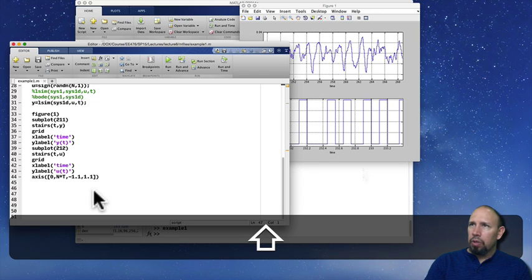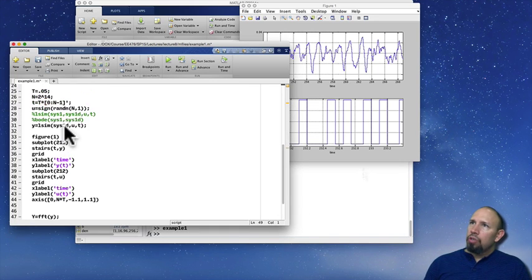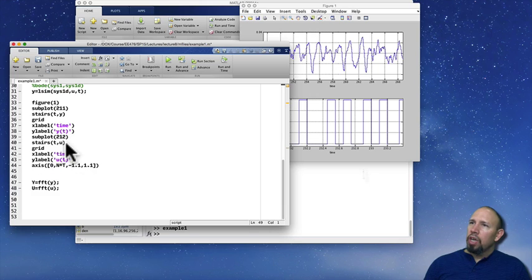So I can define, for example, y equal the FFT. And notice that because we chose the number of data points to be a power of 2, we actually get an efficient calculation. It turns out that for this many data points, MATLAB is definitely fast enough to handle it, and you can hardly even tell the difference. In other words, if it weren't an exact power of 2, it would still be able to do it pretty efficiently. Okay, so now when you do the FFT, it takes 2 to the n values and it returns 2 to the n values.